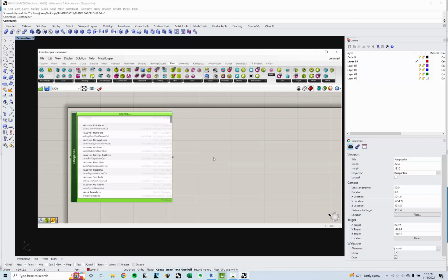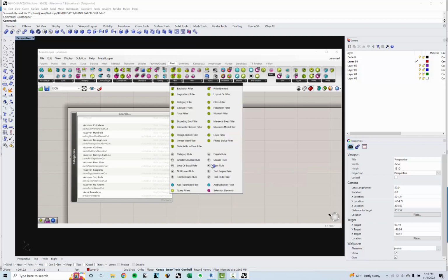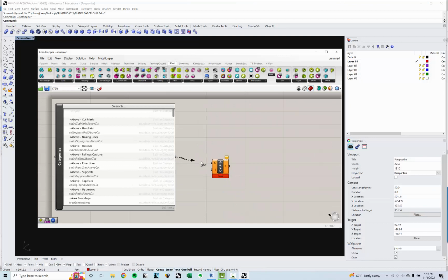And the next thing I'm going to do is use what's called a category filter, which is here. Control click, it's in Revit category filter within filters. And I'm going to grab this. If I use a panel, all it's doing is creating a filter off of this list. I'm sorry, not that panel, this panel. So this is giving me the element category filtered out.